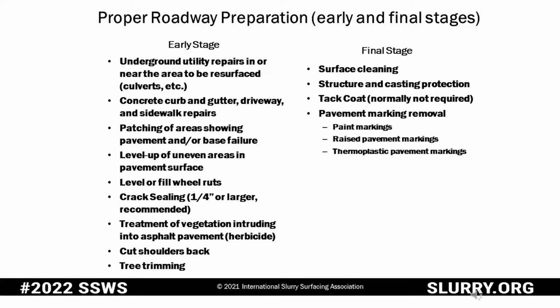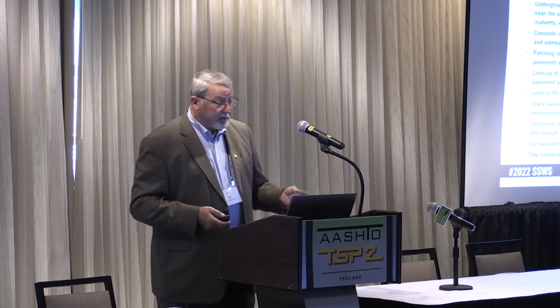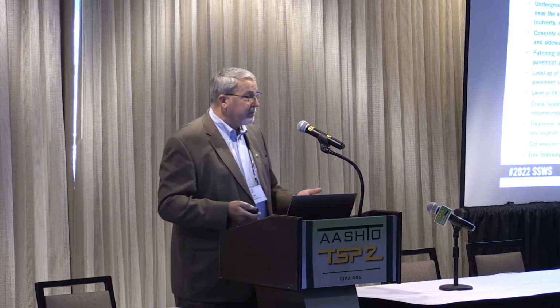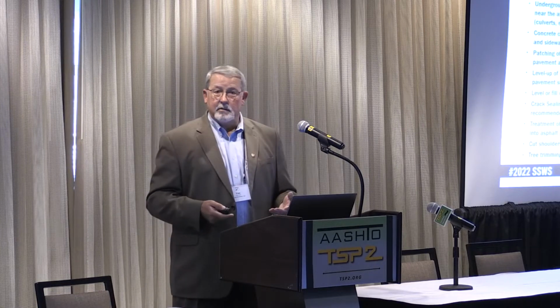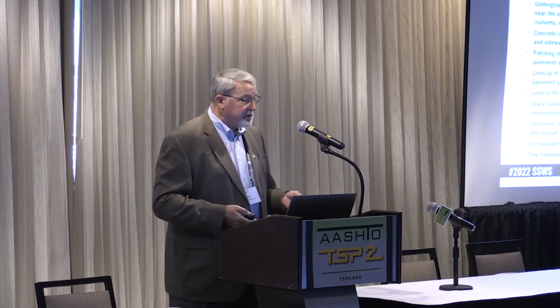Roadway preparation, both early and final stages. You see I got both sides going here. All the underground utility repairs, concrete curb and gutter driveway repairs, patching of base failures or pavement failures, leveling up, we call it structural leveling, leveling or filling wheel ruts, crack sealing 1/4 of an inch or larger is recommended. We heard Dr. Vargas talk about the importance of crack sealing and the results that we get by doing that, and it's very cost effective, a little labor intensive, but the payoff is big.